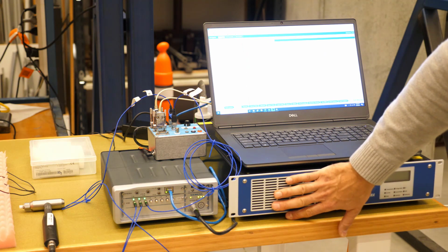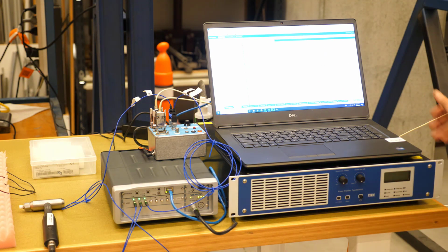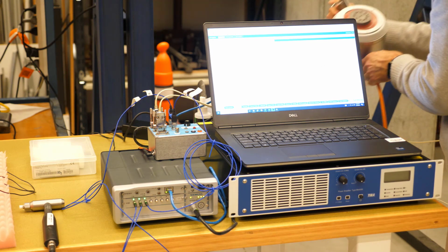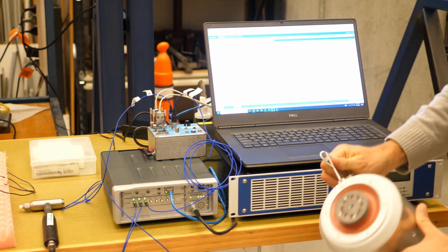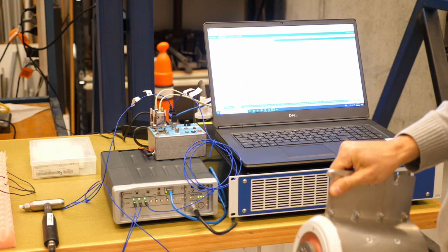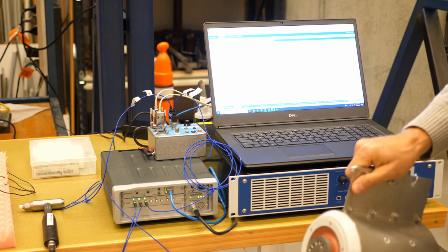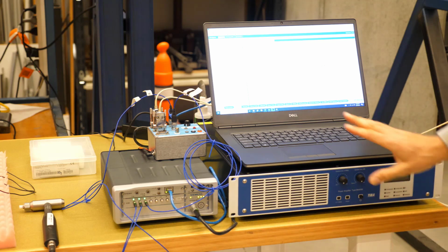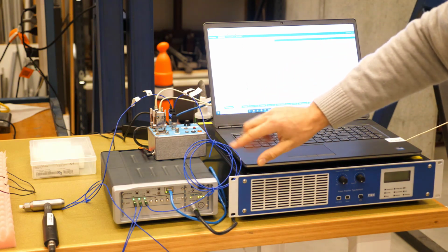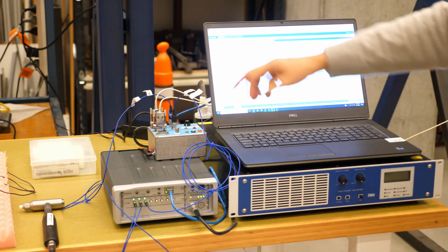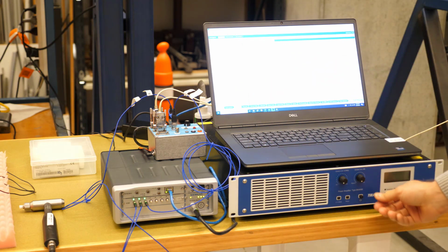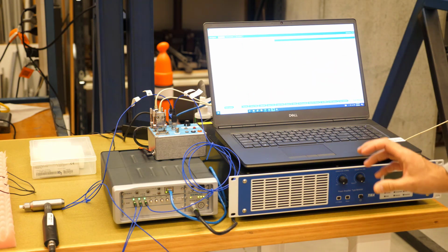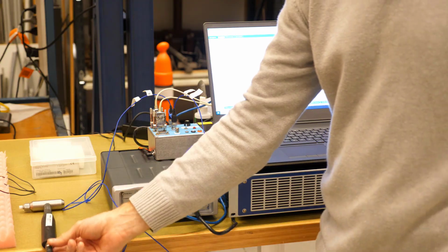And this device here is an electrodynamic shaker. If I was to do a shaker measurement campaign, instead of my impact hammer, I would use a shaker such as this with a stinger mounted to the structure to excite the structure. In that case, I would provide an input signal from the output here on my communication module into the input of the amplifier and very carefully use that to excite the structure instead of the modal impact hammer.